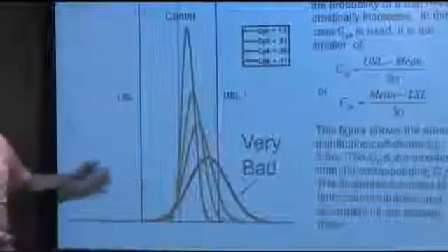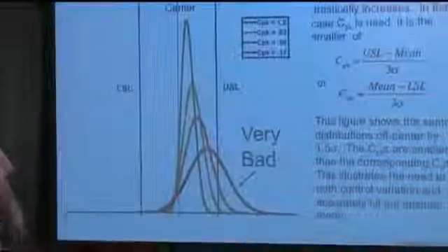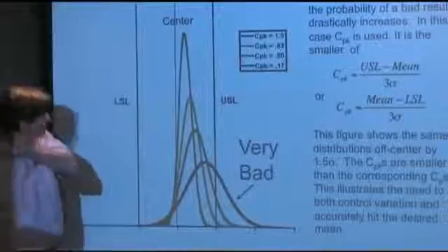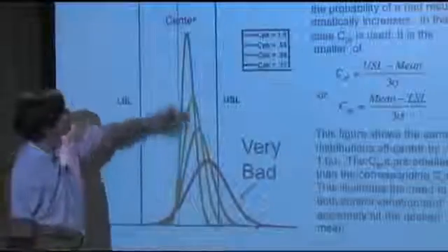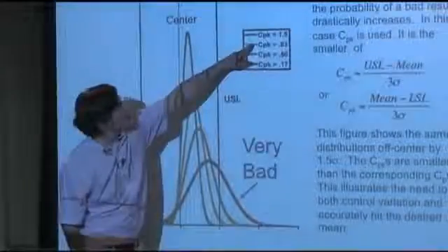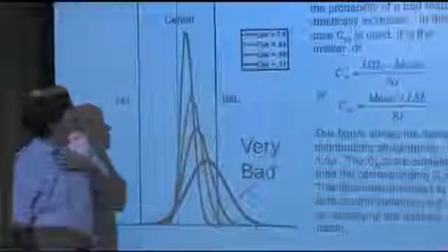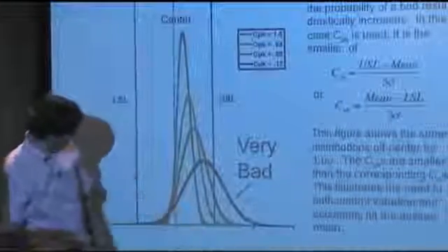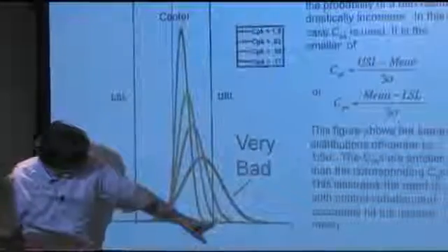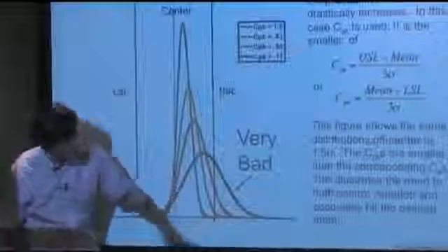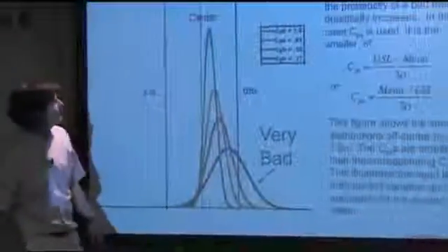And those same curves shifted over 1.5 sigma look a lot less pretty. Our former 6 sigma process now has a CPK of 1.5, but it's still OK. There's a couple of pixels worth of ink sticking out there. The chance of a defect is still very, very small.